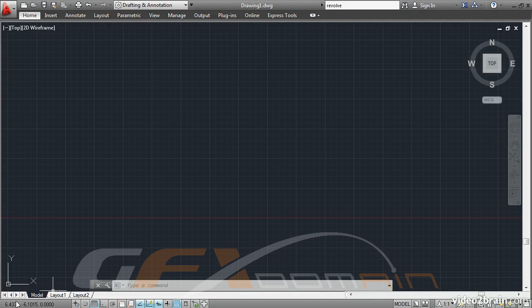At the bottom of the screen, you'll see the coordinate readout. X, Y, and Z coordinates are listed. In this top-down 2D view, I'm only seeing X and Y coordinates change as I move the cursor. This here is called the User Coordinate System icon, or UCS icon for short, and it represents the different dimensions of space. In this case, we're looking at the X and Y axes.